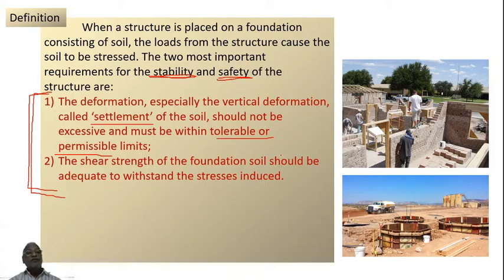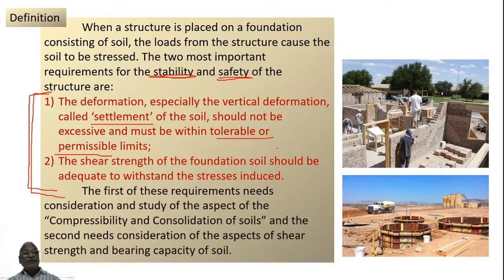Both of these matter a lot in the design of a foundation. The first of these requirements needs consideration and study of the compressibility and consolidation of soils. Settling means it is not the structure going down, but the soil below it is getting compressed.